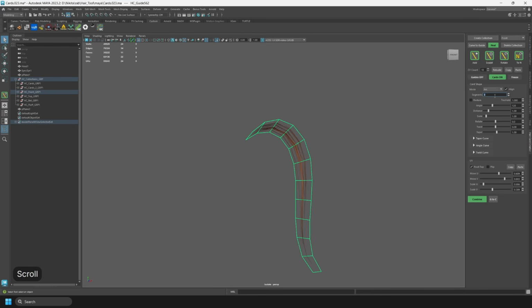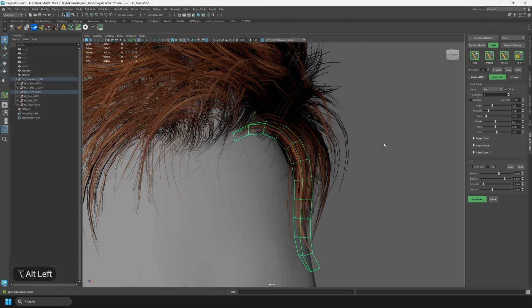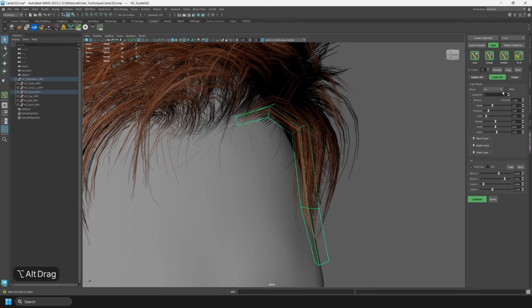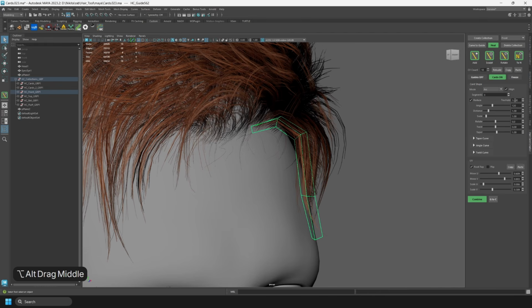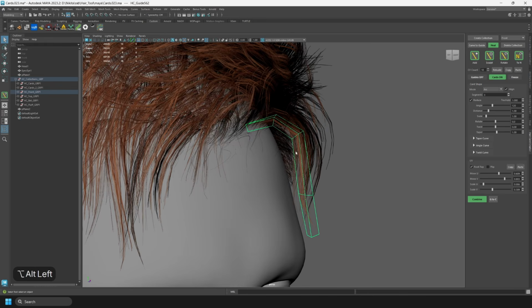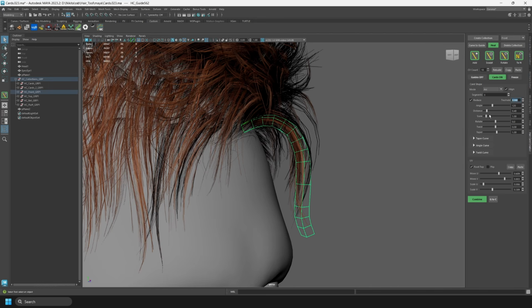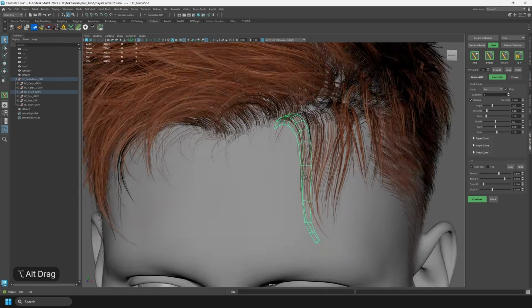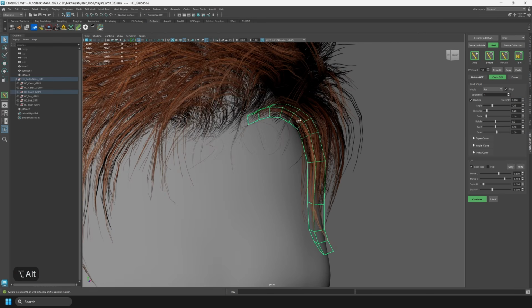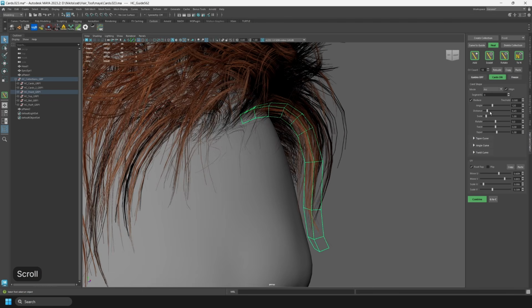Segment sets the number of lengthwise sections on the card. The more segments you use, the denser and rounder the geometry becomes. Reduce lets you optimize the topology based on curvature. Without Reduce, the topology is evenly distributed. With Reduce enabled, edges are removed where the curvature is below the specified threshold. This lets you reduce the polygon count on straight areas while keeping detail where the shape actually changes. Distance sets the spacing between sections. Combined with Reduce, this parameter helps you find the right balance between smoothness and optimization.